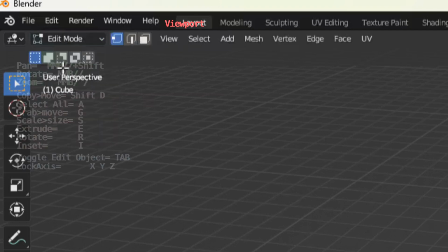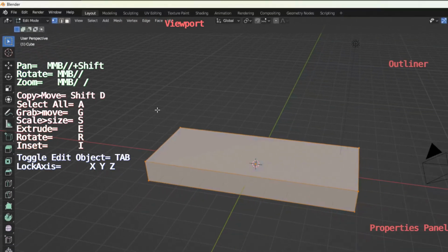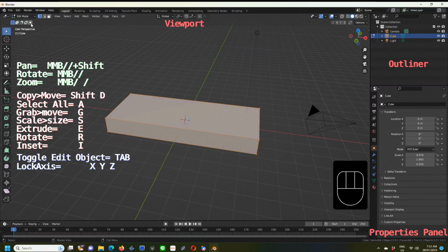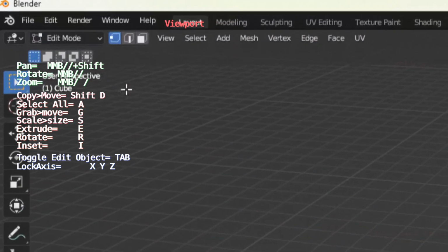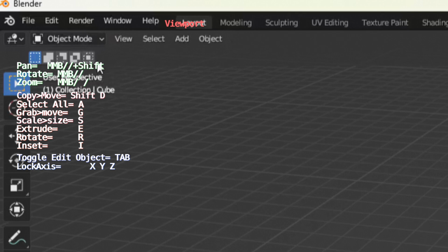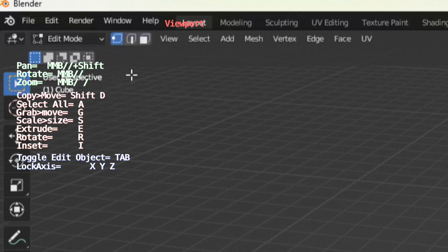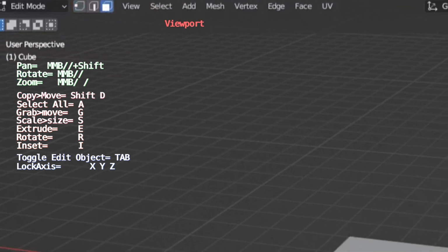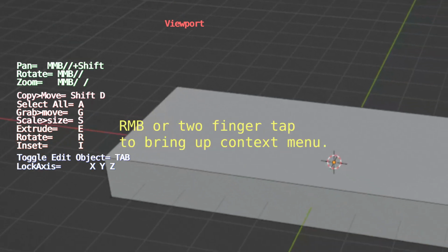We're going to go into edit mode, which we've done here, but you can go into edit mode using the Tab key. Tab selects object or edit mode, and keeps selecting the other when you hit Tab. Now we want to use the face select tool, so we're going to click on the face select tool there. It just makes it a bit easier to view, I think.